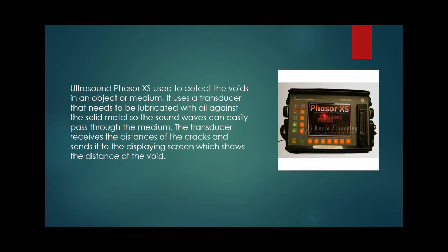This ultrasound inspection is a non-destructive method in which beams of high-frequency sound waves are introduced into the material for the detection of substance flaws in the material. The sound waves travel through the material, and when there's a loss of energy, they're reflected back from the cracks or the holes to show that there are cracks or holes in the material. This is where they are located. This is the way the flaws are highlighted in the material.